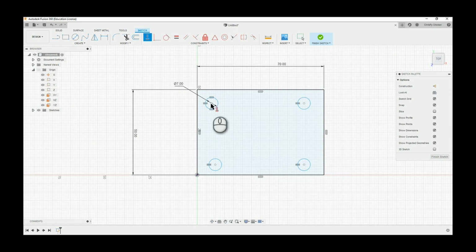We're going to see. So you can just select center points, and that will indicate that they are horizontal with each other. Once again, select the center points, and they're horizontal with each other now. Now do the same thing, but with vertical points. You can see it snapped into position so it's vertical, and I'll probably do the same thing here.